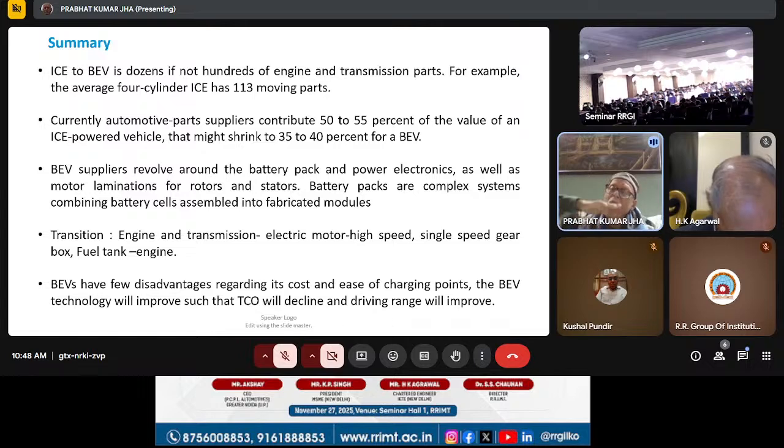Whenever you go for a long drive, you charge it 100%. Only for long drive 100%, for local or daily use only 80%. And never ever forget to store these batteries at 0 to 25 degrees C.